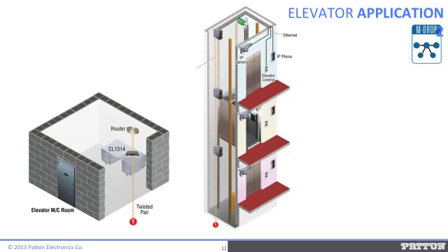When this elevator manufacturer released the current generation of control units, they eliminated the RS-485 interfaces in favor of the newer standard Ethernet. This application, unlike the first elevator story, does not require lots of bandwidth. The customer just needed access to the elevator controls via Ethernet over older and multi-dropped wires. Using a CopperLink MD in place of the original RS-485 modems allows for this transition from serial to Ethernet without having a single change to the physical infrastructure, saving the customer time and money.